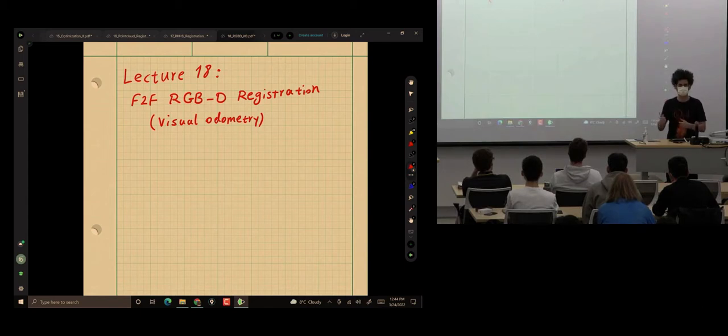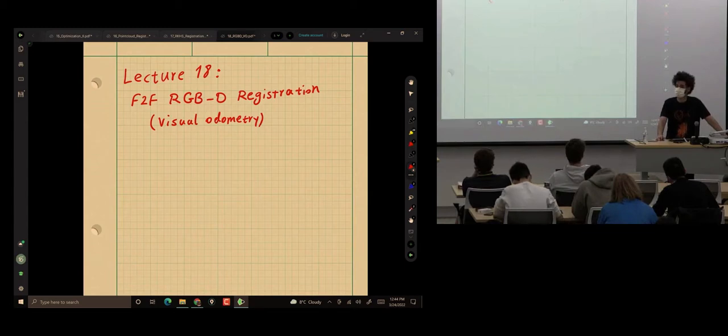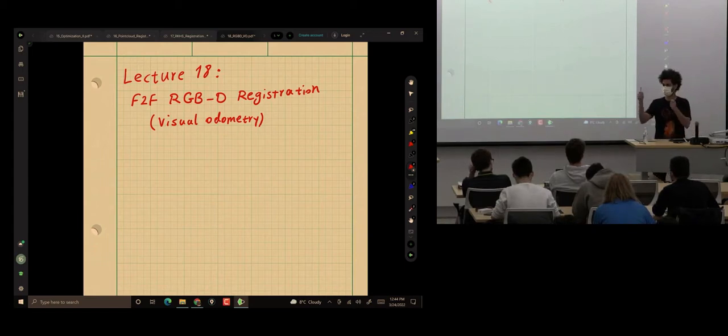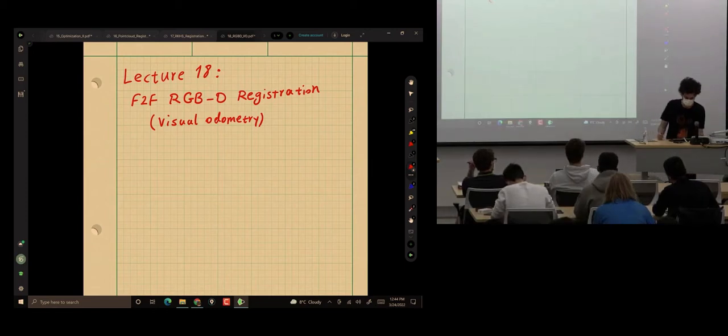If you're working with a sliding window and rely on local constraints to improve your estimate over a window of time, that's usually called odometry. So frame-to-frame registration is the building block. It's the simplest way of solving that odometry problem. So it's necessary to learn it, then you can build on it by solving many of these frame-to-frame problems at the same time over a window of time. And the window slides over time, right? You add new frames, you ignore old frames. That's the idea.